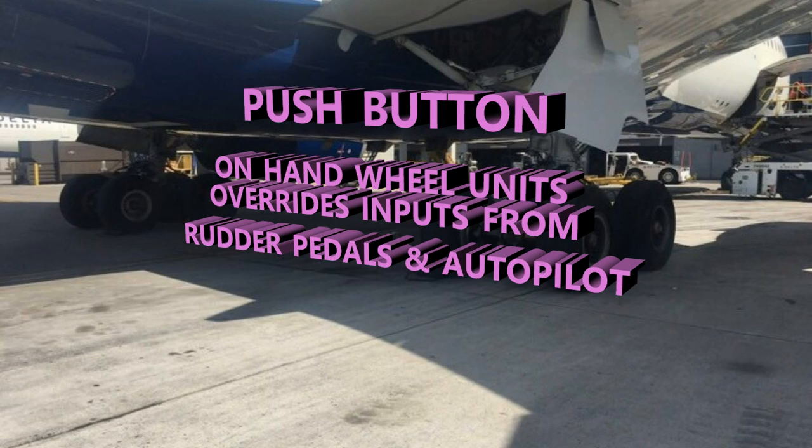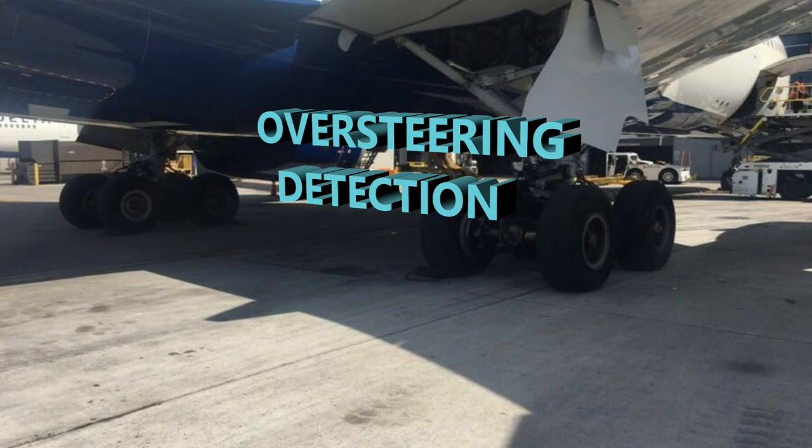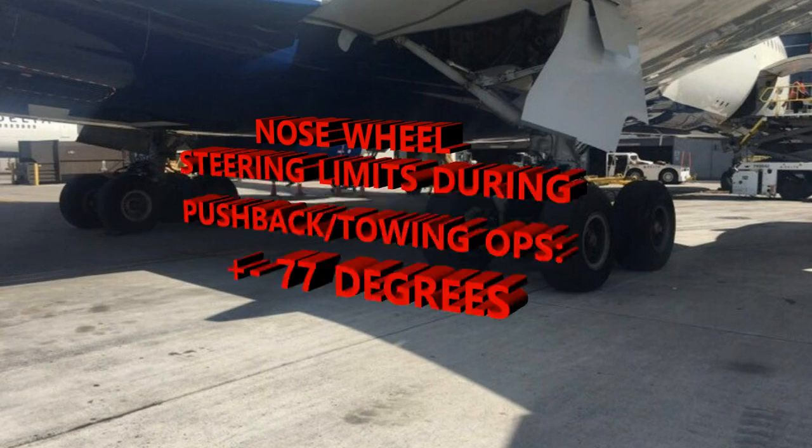There's also an oversteering detection. One thing that's important about the angles when the wheels move from left to right is how far they can go, because they can't go 90 degrees. When the aircraft is pointing straight ahead and the nose wheels turn left or right, there's a certain maximum number of degrees.